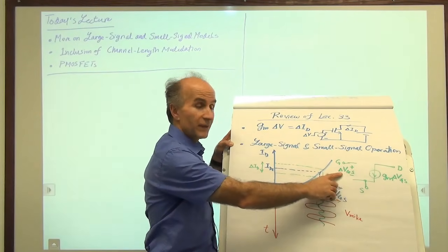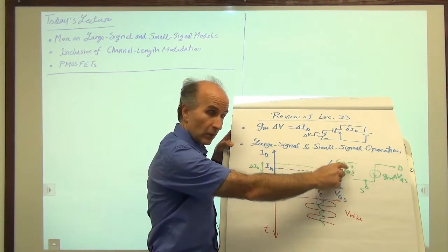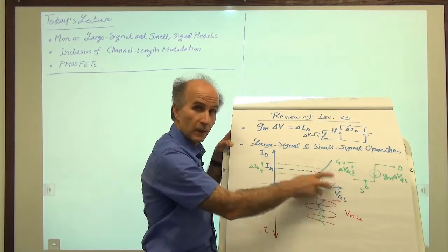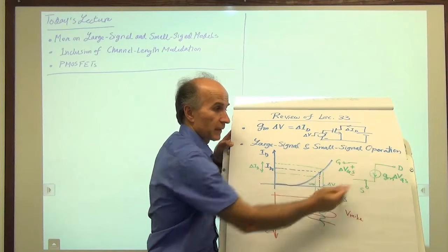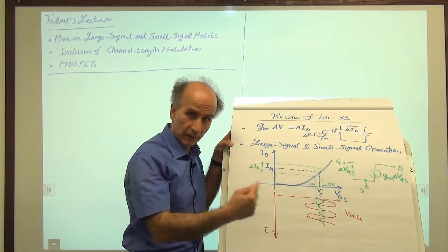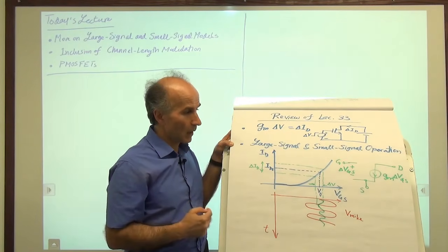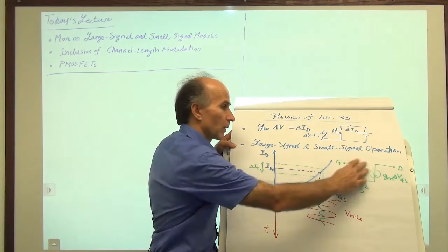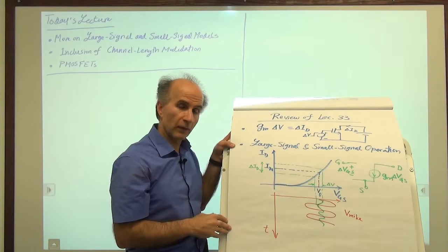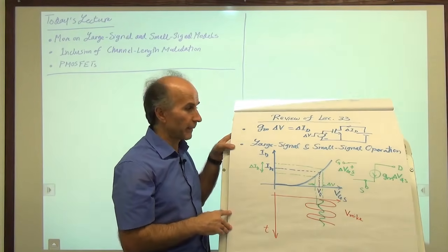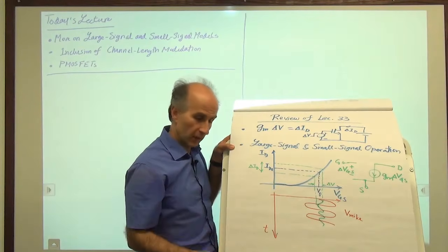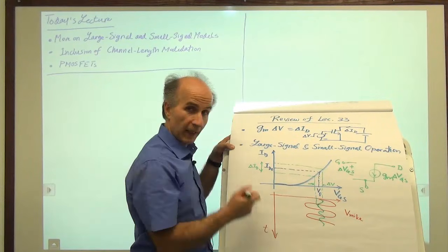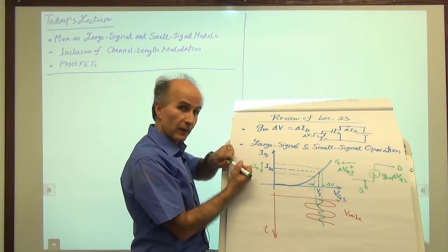The gate source change or fluctuation goes between gate and source, is applied there, and the current change is represented by Gm delta VGS. All right, so this is what we call the small signal model of the transistor. And in fact, oftentimes, instead of delta VGS, we just write one voltage, and usually with lowercase to indicate that it's small signal.